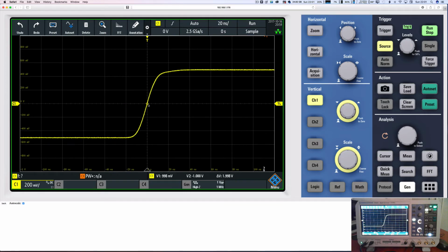So that's now triggering in the center of the waveform on the 0 passing point, because this waveform is, I think, 1 volt peak to peak, which makes sense from around here. It's just between the 400 and the 600, so we're about 500 millivolts positive, 500 millivolts negative. So that shows you your triggering.